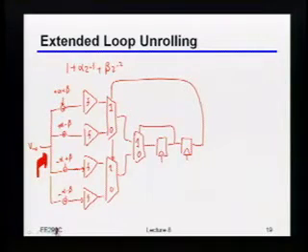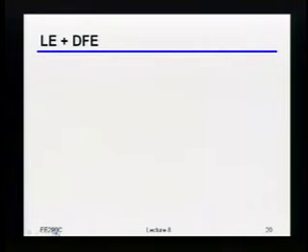Okay, so there were just a few practical issues that I want to briefly mention. This one I think we mentioned a little bit last time already, but just to make sure it's clear to everybody. As hopefully you saw from the homework, a lot of times you'll actually combine a linear equalizer with the DFE. And in some senses, sometimes you'll even just build the DFE to make life easier in terms of actually doing the linear equalization. Okay?